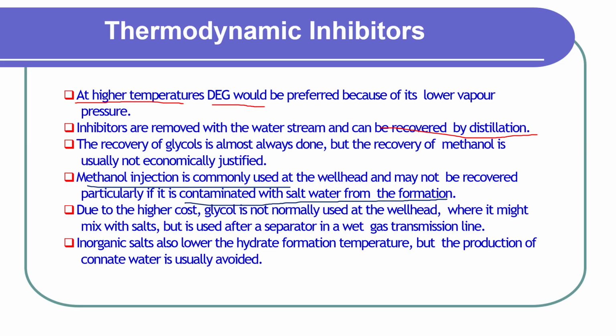So another fact: if you're injecting at the wellhead, since the chemical will be mixed with salt coming from the rock formation, it's better to inject methanol, because methanol will not be recovered. If you are injecting after the separator, let's say through the pipeline, when you have that wet gas stream in the pipeline, it's preferable to use glycol, although glycol is more expensive than methanol, because you can recover the glycol using distillation.